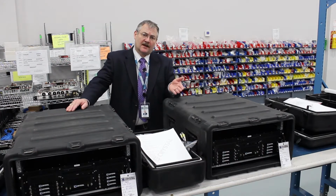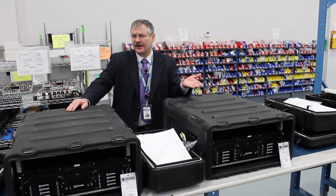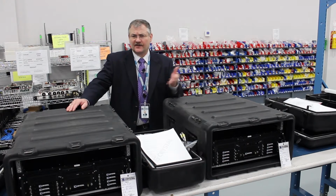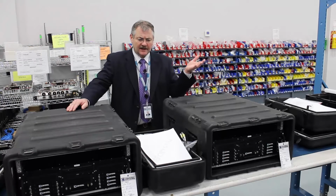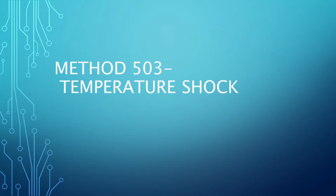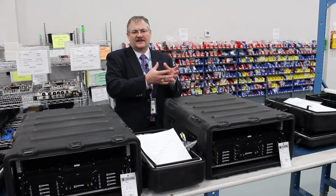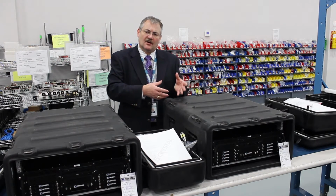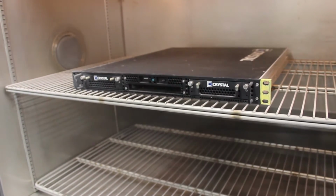Wanted to spend a moment talking about MIL-STD-810, and we're talking about MIL-STD-810G in this case. Other customers may specify a different revision, but we just happen to be talking about G at this point, and wanted to talk for a bit about temperature shock and what that test is, and that's method 503. What this test is supposed to do is simulate the transition of your equipment from, say, a hot environment to a cold environment very rapidly.